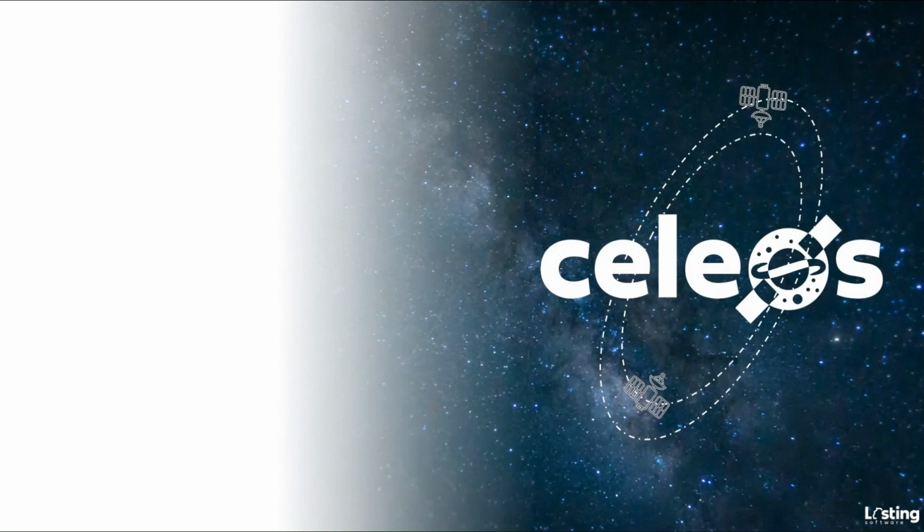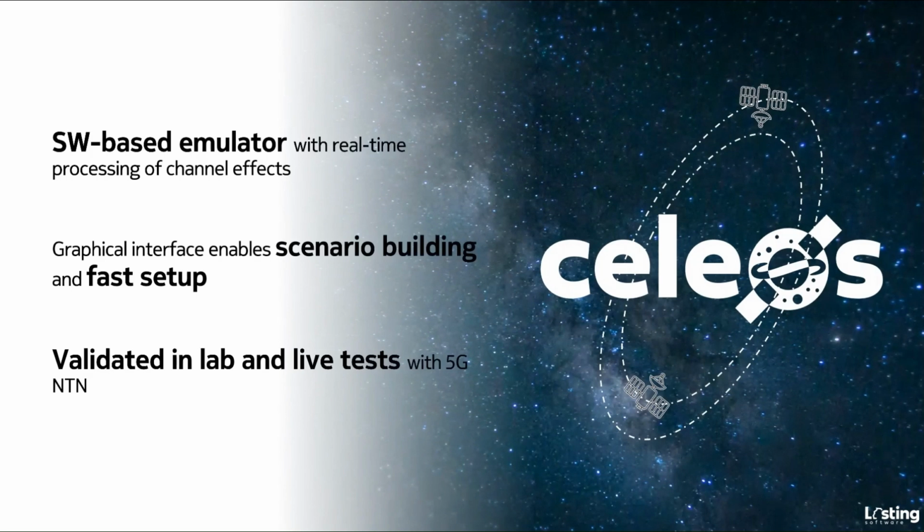To validate CELEOS, we tested it in a full 5G NTN setup. A satellite channel was emulated between an SDR-based gNB, g-Node B, and user equipment. The test confirmed CELEOS's ability to accurately reflect link impairments while supporting real-world 5G operations end-to-end.